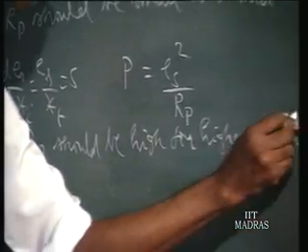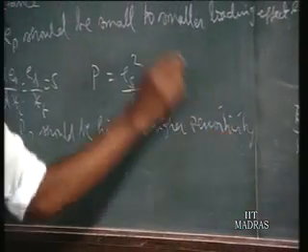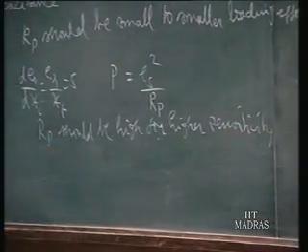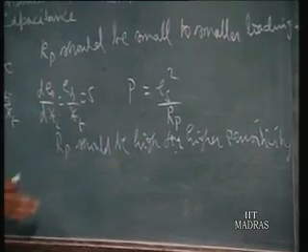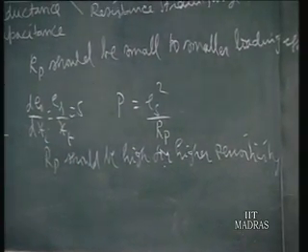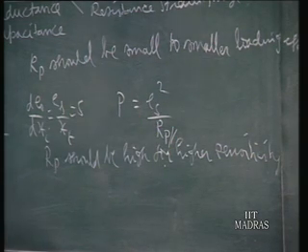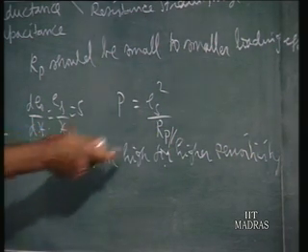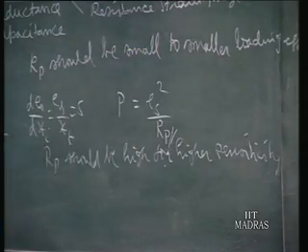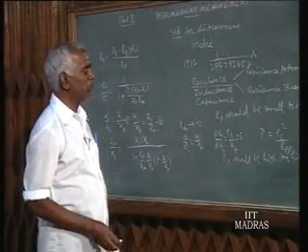So, now you find contradicting requirements for Rp. Rp should be small for smaller loading effect, but it should be large for higher sensitivity. Hence, we should be careful in selecting Rp. If you increase it too much, you will find you have got loading effect. These are the considerations when selecting Rp.